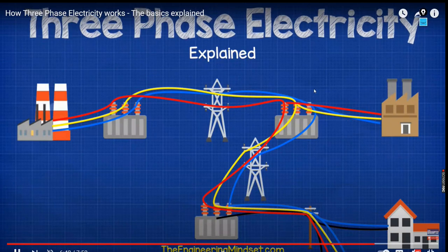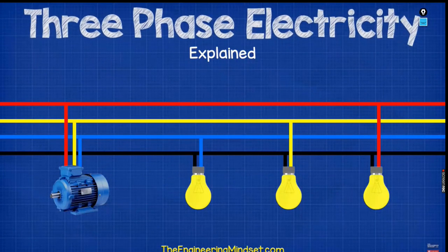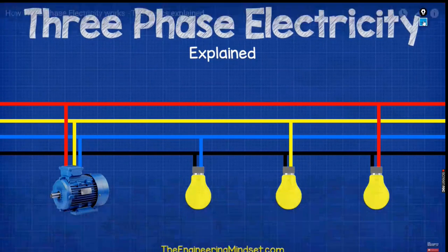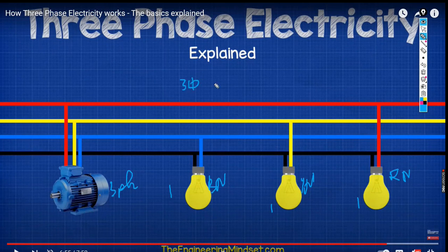This is with respect to the application where we are going to use it. This is the three-phase power connection with a four-wire system. I told you, the three-phase four-wire system: from that, the three wires R, Y, B are connected to a three-phase load. Then B phase and neutral is single phase. Then Y phase and neutral is single phase. Then R phase and neutral is one more single phase. This is the three-phase, four-wire AC supply system.